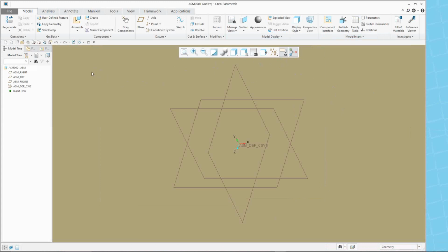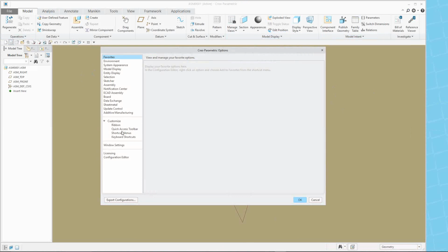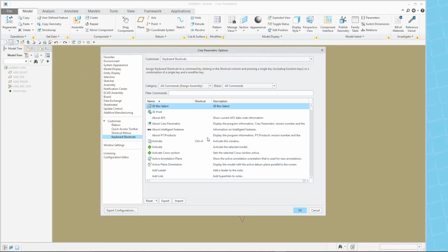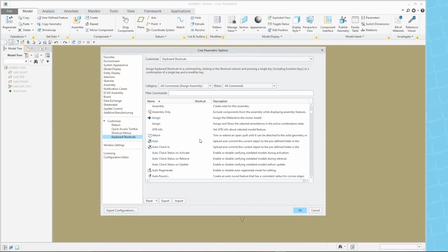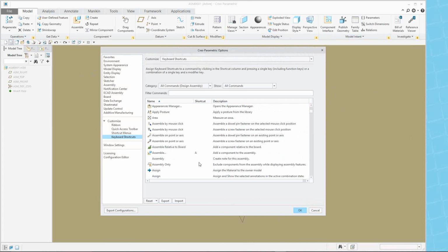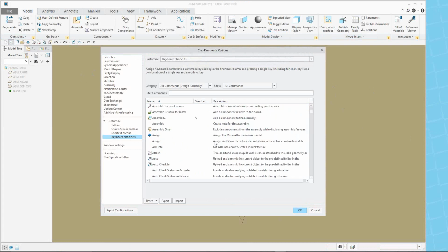As you are creating map keys, or manipulating your keyboard shortcuts, keep in mind that it won't let you use something that's already there. Even in our map keys, if I put in letters that are already used by something else, it will flag me and tell me, just like it did when I did it inside this dialog box, that that command or that keystroke already belongs here. Do you want to override that?